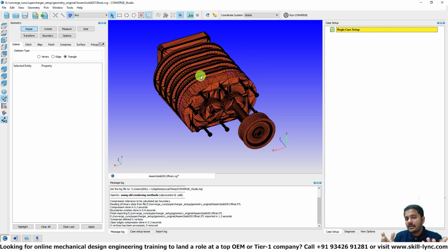Now usually if you're working for a company that makes devices like this, you are interested in performing a CFD simulation to understand the relationship between the pressure ratio and mass flow rate. That is, for a given mass flow rate, how much the pressure can be increased. And you might also be interested in obtaining the final temperature of the compressed air, because since you're compressing the air, its temperature is going to rise, and if the temperature is higher, the density is lower, and depending on how high the temperature gets, a cooler unit might be required to cool the pressurized air.